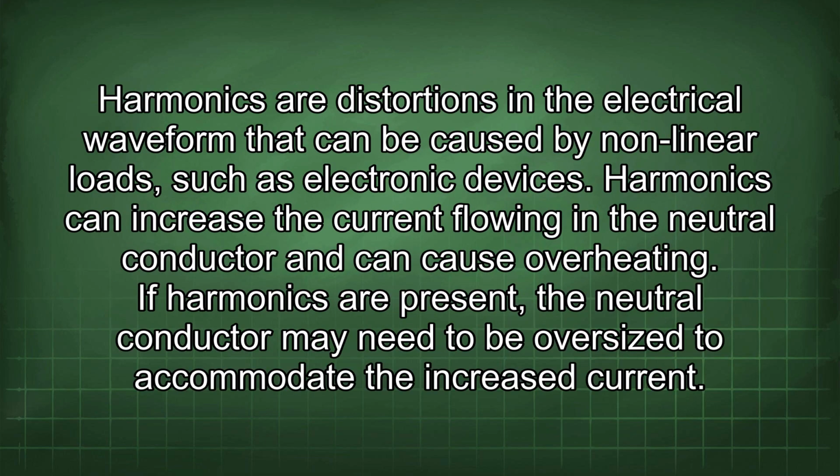Harmonics are distortions in the electrical waveform that can be caused by nonlinear loads such as electronic devices. Harmonics can increase the current flowing in the neutral conductor and can cause overheating. If harmonics are present, the neutral conductor may need to be oversized to accommodate the increased current.